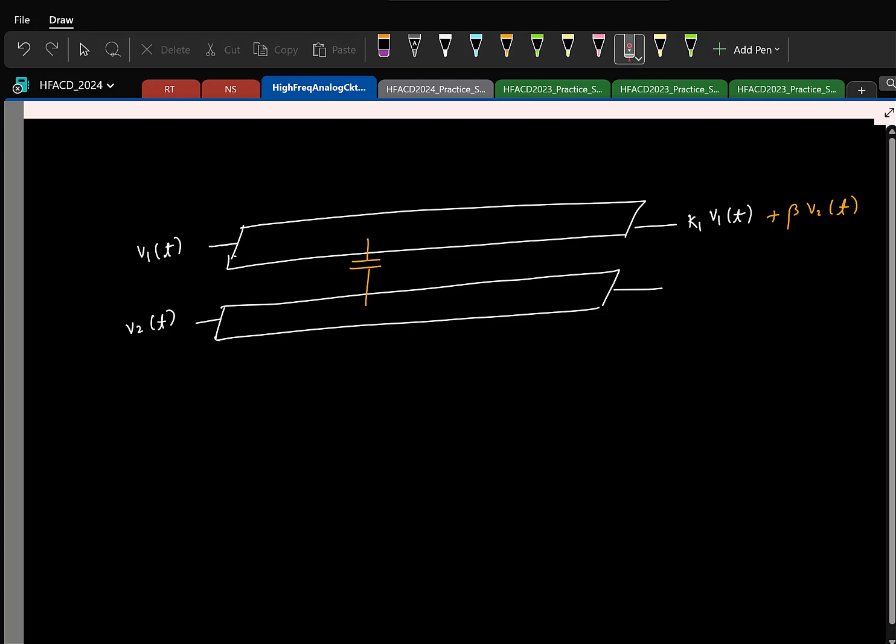So that is not great, because you see that this signal is kind of interfering with your actual signal. Is that called coupling? You can call it coupling, interference coupling is also fine. And not just that, if you look at the signal here also, ideally you want it to be V2, but you will have some interference. As I say, it's not like only your neighbor should not dump their garbage in your house. You should also not dump your garbage in their house, right? It should be mutual.